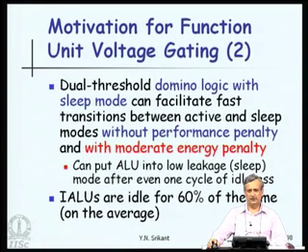It is possible to incorporate dual threshold domino logic with sleep mode circuits, which facilitate transitions between active and sleep modes very quickly, with not much performance penalty, in fact just 1 cycle, and with very moderate energy penalty. If there is a very sharp transition, then usually there is an energy penalty as well. And that is the reason for concern.